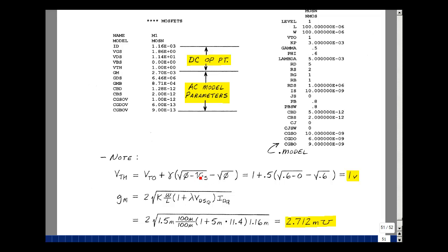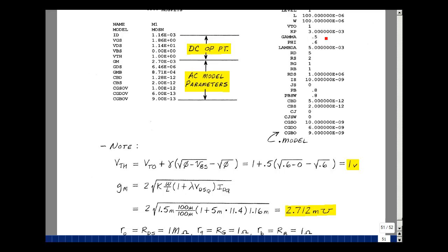And when you buy an individual transistor, that's always the case. You're going to short those two together because of this term being present. This is our formula for GM. Let's plug in the values here. K is half the value of Kp.